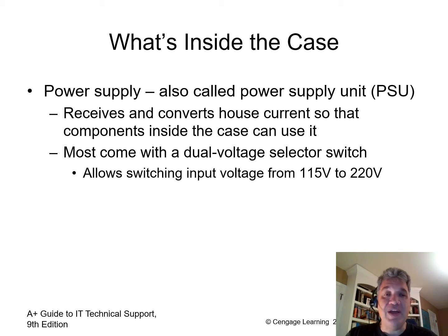If you're running straight from battery power, then it would not be as hot because it doesn't have to go through that conversion. But all PCs and servers for that matter are set up in the same way. Power supplies do not have, it's worth noting, any user serviceable parts inside. So you should never, under any circumstances, open up a power supply to do any troubleshooting or try to replace any components.